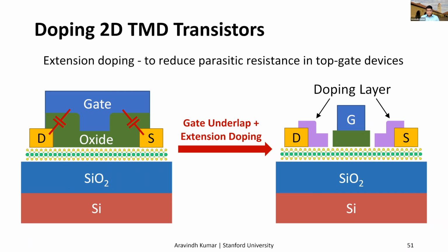To your second question, yes, there is an asymmetry between the source and the drain. Generally, we expect the source resistance to be higher because the drain resistance has this large voltage across the Schottky barrier. But the RC that we estimate is the sum of the two. So multiplying the two should give you the total parasitic resistance. Okay, thank you.